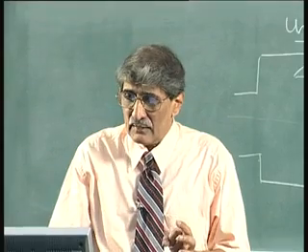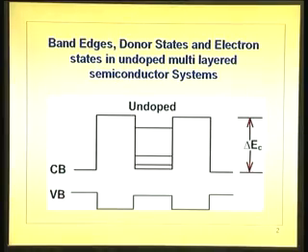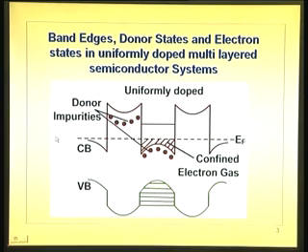Discontinuity that you have is because of the difference in the band gaps. Now, this is actually a situation where you have wide band gap material, conduction band, valence band of a wide band gap material. Okay. This is what actually we have discussed last time. A N type material aluminum gallium arsenide joined with the P type gallium arsenide, narrow band gap.